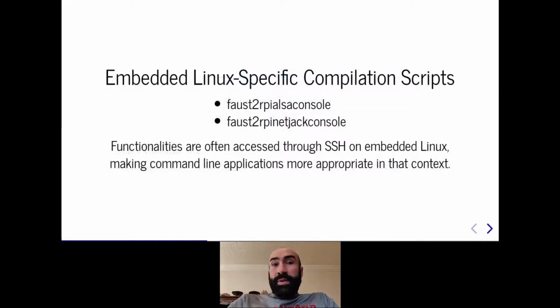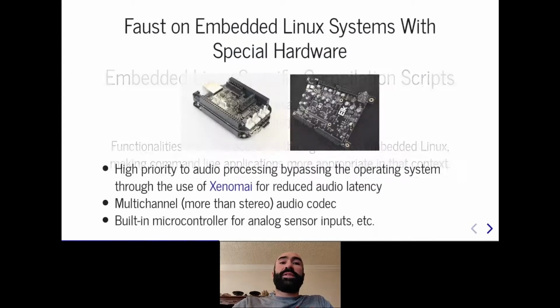Designing musical instruments around embedded Linux systems also implies the use of an external microcontroller, which is usually connected through USB or I2C, since the CPUs used on these platforms don't have built-in ADCs. External controllers like MIDI controllers or communication protocols such as OSC can be used as well with Faust, but it defeats the purpose in this context by externalizing some parts of the instruments.